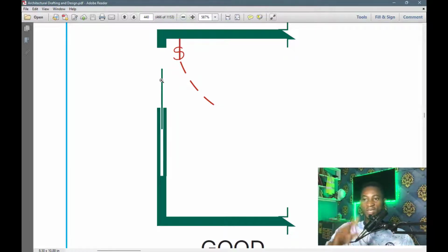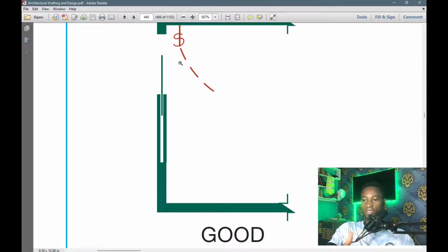but let's learn together. So this is a switch here. So it's telling us the good way. When you open a door, the space where the door swings to, you just have to place the switch at that area. So this is the good area, a good example.